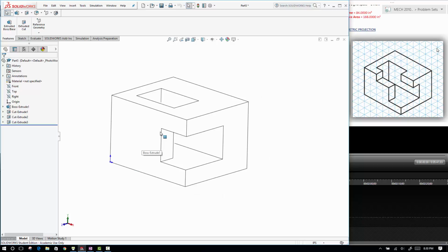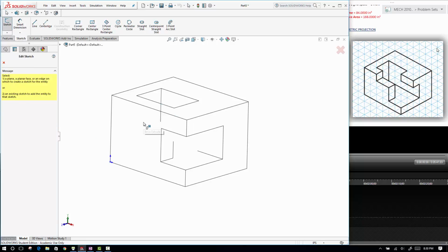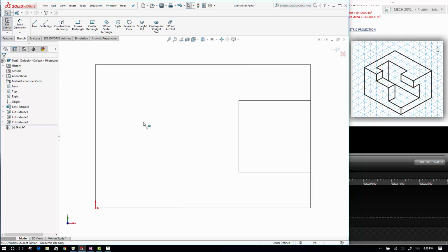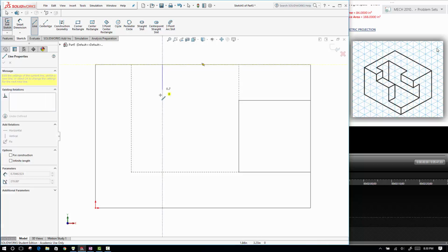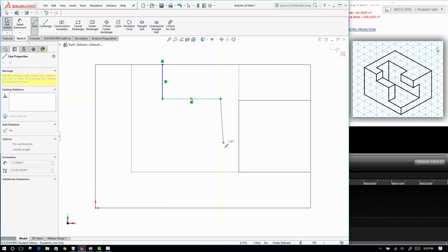just line mode. And what I now need to do is take out this material. So what I'm going to do is cut this whole piece out and go back a distance of 2. So I'm going to go sketch, select this surface, and again I'm going to make my hidden lines visible so I can grab things that I want, and I'm going to start my line here, not on this line. I have to come over 1 from that. So I'm going to go down, and I'm going to go over. I'm purposely missing some things so I can put my constraints on afterwards.